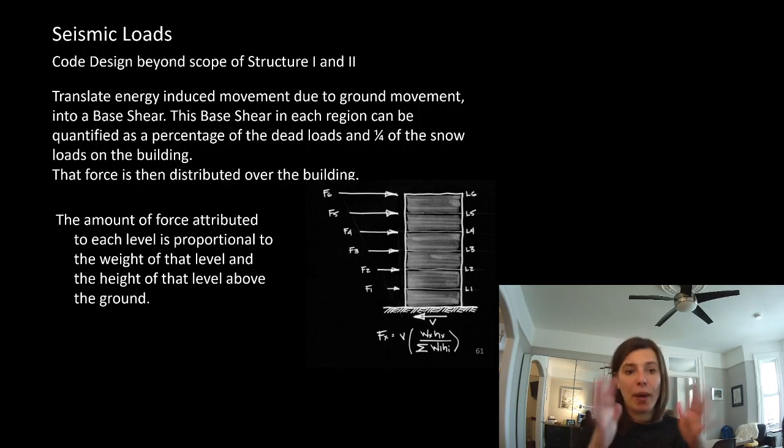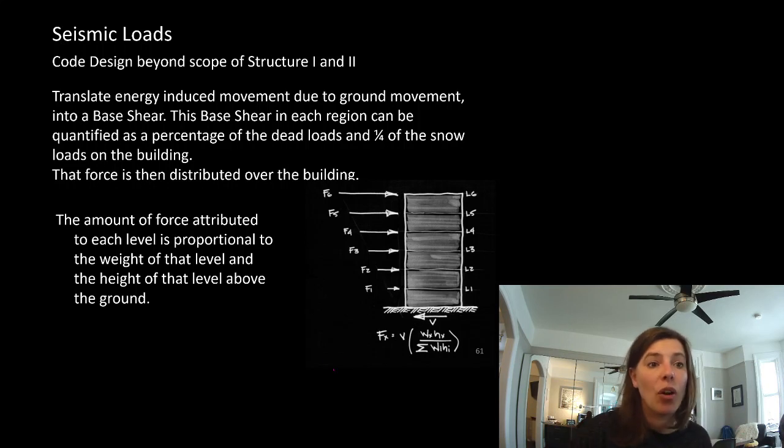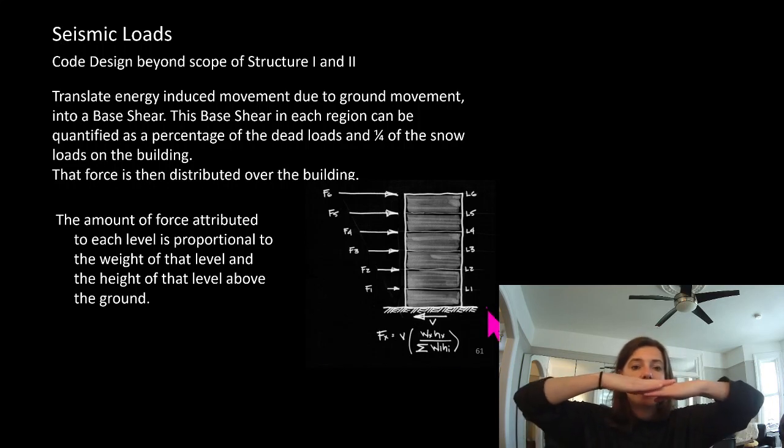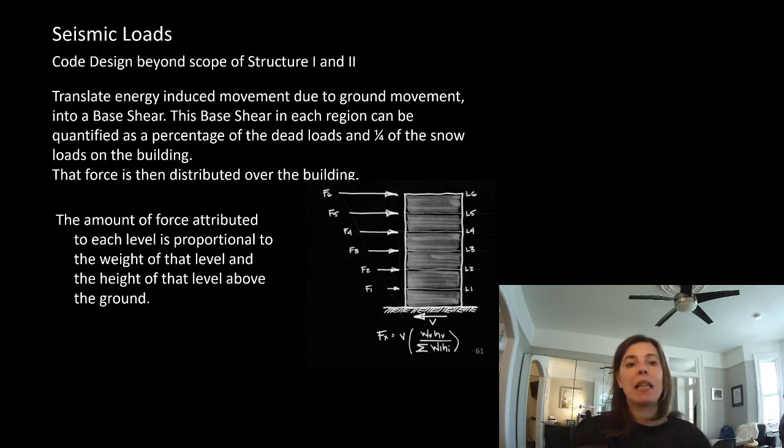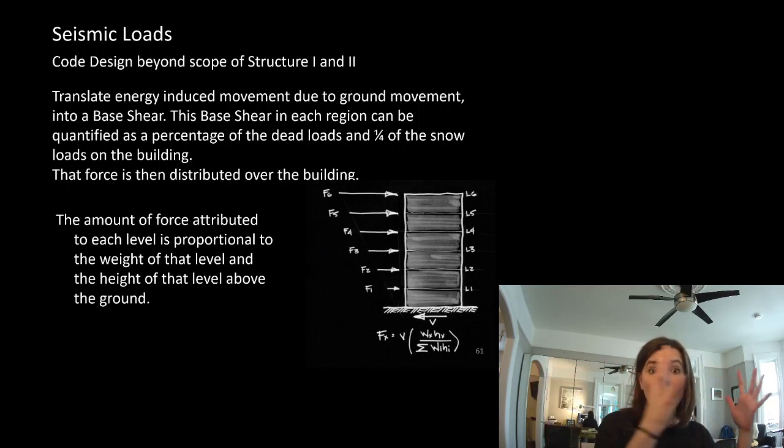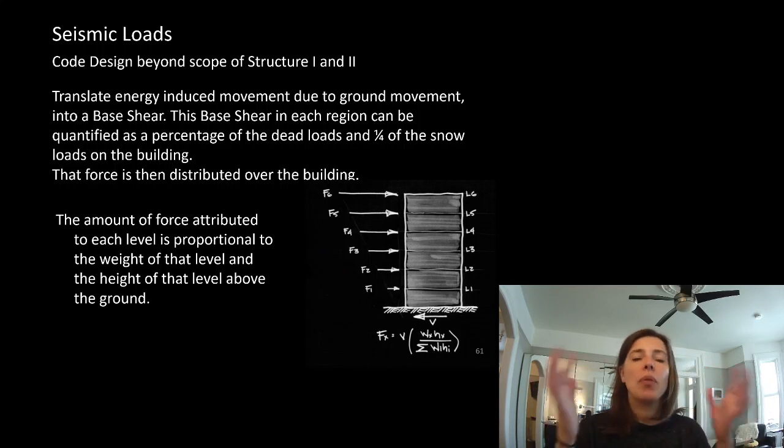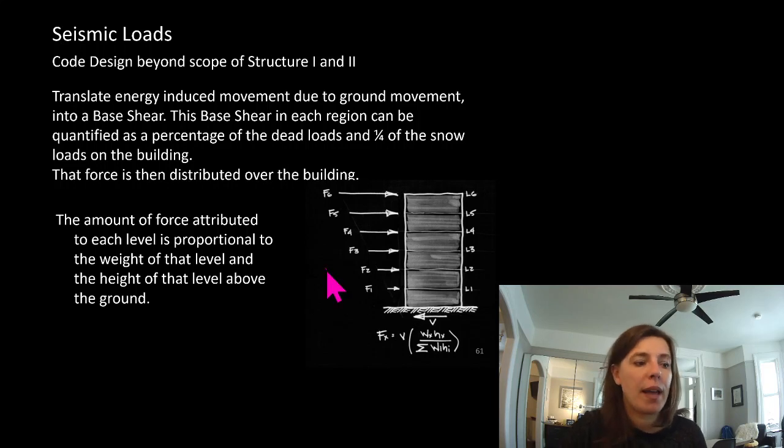And you care about that entire base shear, or what is the force that the building is trying to slide against the ground as. So that's what you're going to calculate. Remember in our wind load, we figured out what the total shear of our building is? Well, that's what we're going to do for our earthquake as well.